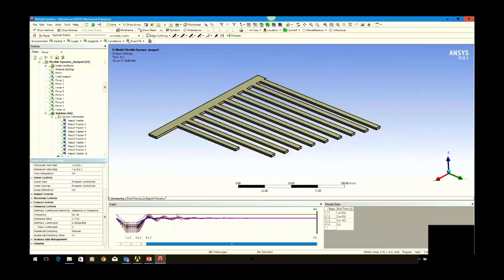You can say, okay, I think a frequency of 100 is the base one that I want to damp out, and then you choose your damping ratio appropriately. This damping ratio can be determined experimentally with some simple tests. You just look at the amplitude of successive waves. I won't go into too much theory on it, but it's quite easy to determine.